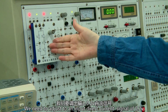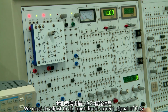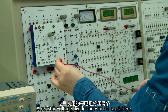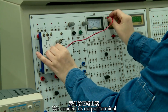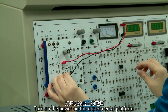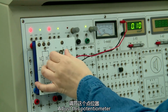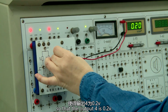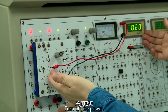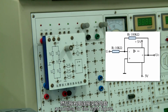We need to adjust to an input direct current signal of 0.2 V. A resistor voltage divider network is used here. We connect its output terminal to a digital voltmeter. Turn on the power on the experimental platform. Adjust this potentiometer so that the output is 0.2 V. Turn off the power. Then connect the experimental circuit according to the right figure.